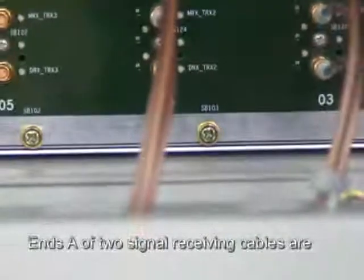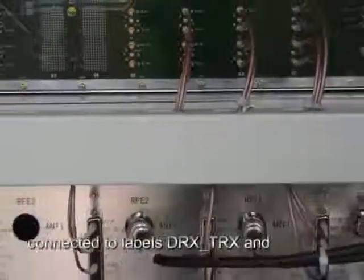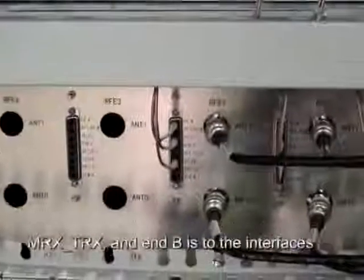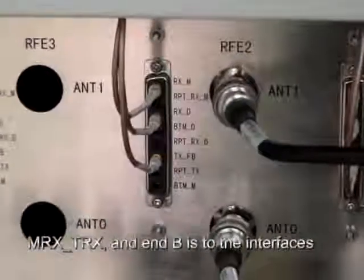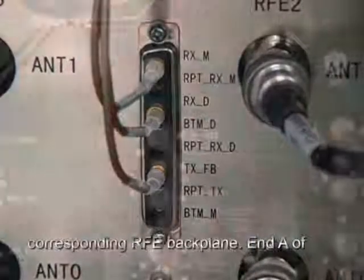The ends A of two signal receiving cables are connected to the labels DRX-TRX and MRX-TRX, and end B is connected to the interfaces identified as RXD and RXM of the corresponding RFE backplane.